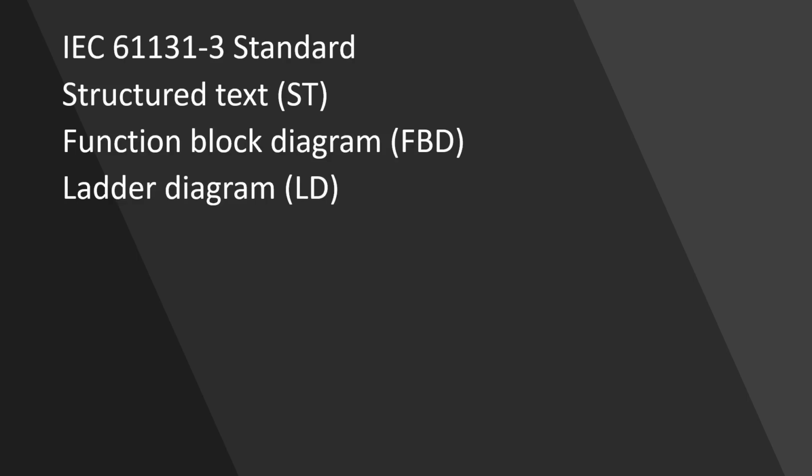Third is ladder diagram, LD, which is very intuitive as well. It kind of reminds me of some relay schematics, and that's why it is easy to understand for most of the people. As far as I know, it's very popular and kind of de facto in process automation and factories. But on the BMS side, where I work, it's not commonly used, at least in Finland.